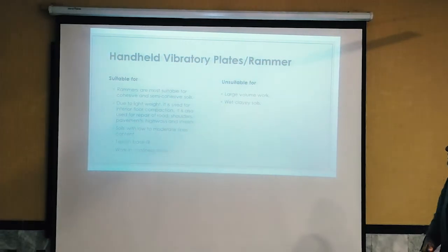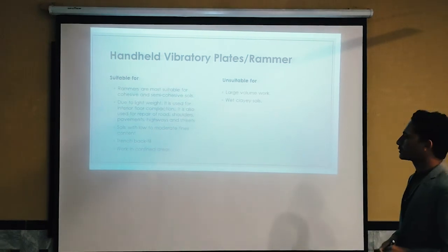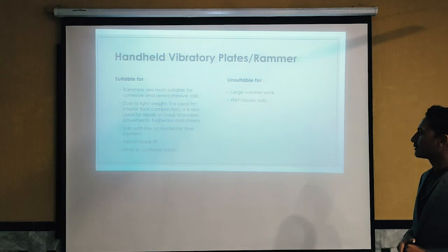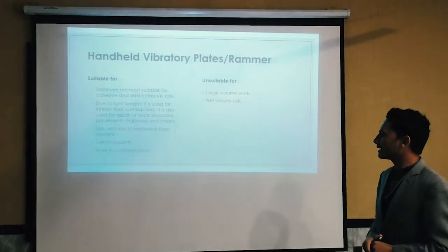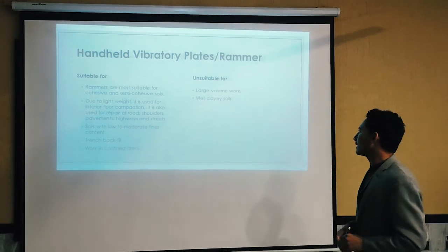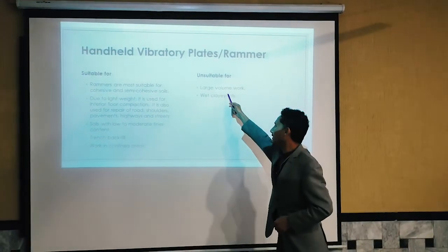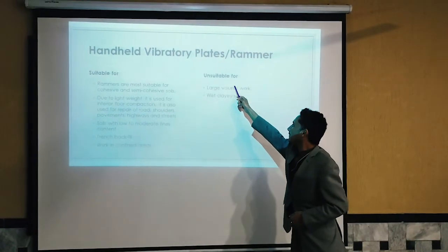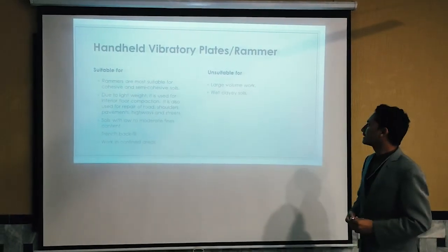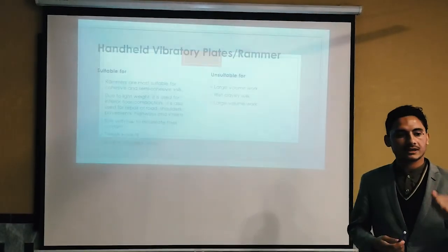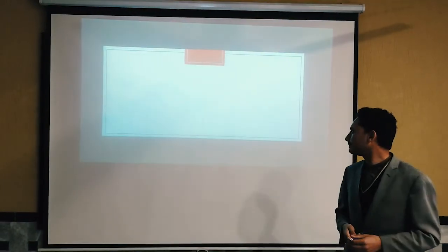It is also used for the repair of roads, shoulders and highway streets, soils with low to moderate fines content, and trench backfill work in confined areas. Unsuitable for large volume work, which I have told you before that we can't use it. Wet clay compaction also, we can't use this compactor.